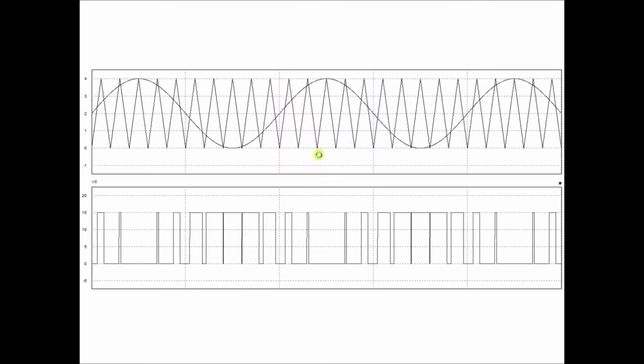The sine wave is stored internally in the buffer, which is done by an internal harmonic oscillator or an external function generator. This allows the whole system to be set under ideal conditions. After some time, the algorithm switches itself to the sine wave produced by the load current. The triangular wave is generated having 50 kHz frequency. The comparator is implemented. When sine is greater than the triangular wave, PWM goes high. When sine is less than the triangular wave, PWM goes low. Thus, an SPWM pulse is produced.